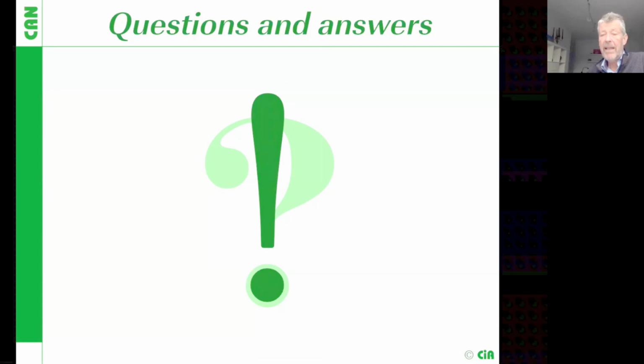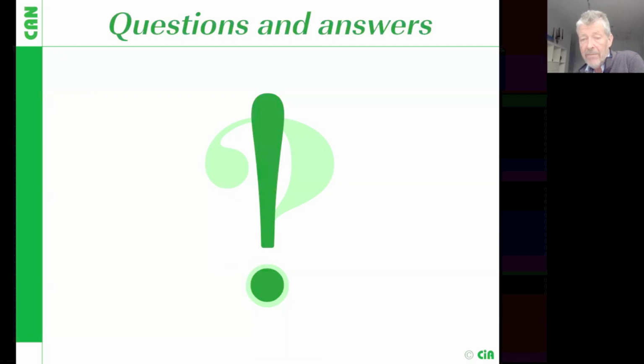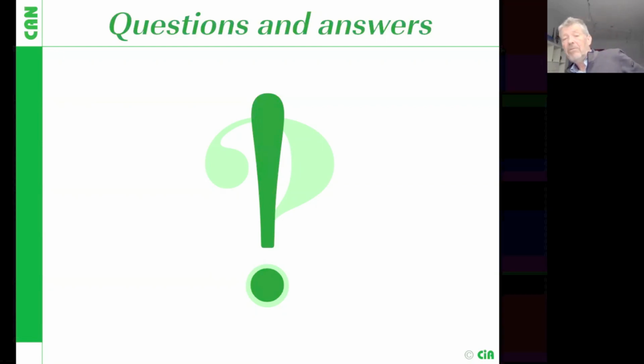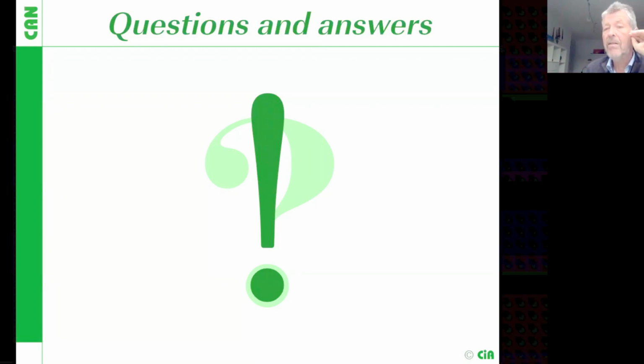Bit stuffing is in CAN XL the same as in CAN FD and in classical CAN, meaning after 5 consecutive bits with the same level a stuff bit is inserted. No, that's not right. As I said, we will do this after 11 bits, and this is just in the arbitration section, and afterwards we also have some fixed stuff bits in the frame.